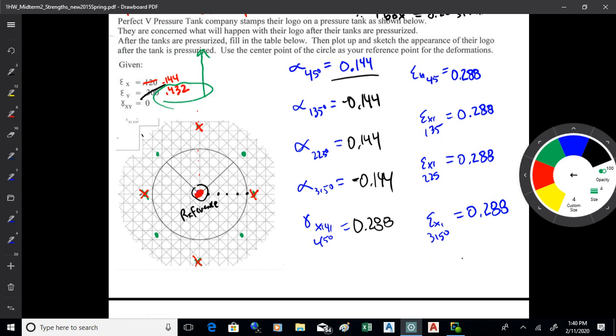Now, not only will that line stretch out, it's also going to rotate over. And that's alpha. Alpha is how that line rotates. Positive is counterclockwise, negative is clockwise. Now, see, this is an angle in radians, but it's also approximately equal to the tangent of the angle, and that's going to be the ratio of the two sides of a right triangle there.